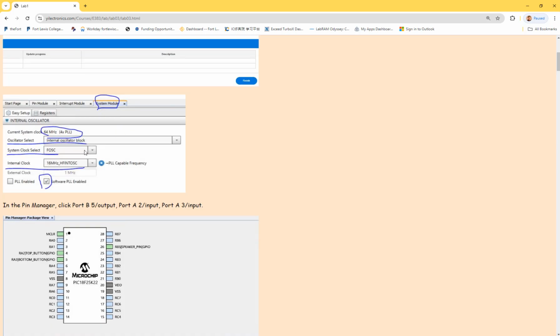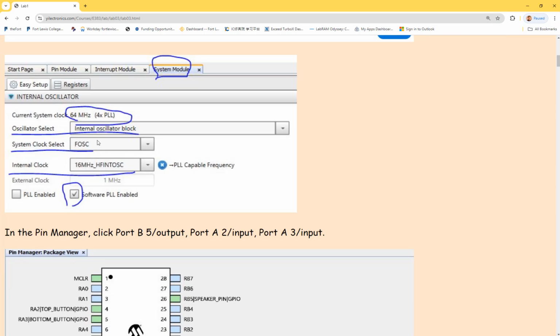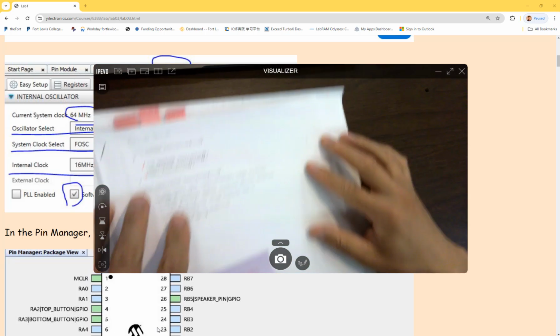If you look at these settings, it mainly sets up the crystal, because the microcontroller has a certain frequency running over the core, and 16 megahertz is the frequency that we use for all the labs. However, you can change it to something else, but we are not changing it for any of the labs. So at the very beginning, you set it up as 16 megahertz using that nice little GUI. If you don't use that GUI, there are definitely other ways to do it. I'm going to show you this really quick, even though it's not really clear.